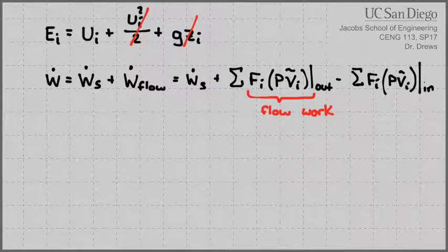That pressure generally is developed in one of two locations. Either you have shaft work, like a pump driving stuff through your reactor, that can be the origin of where that pressure comes from. Or if you're trying to make a Rube Goldberg kind of reactor, you could set everything up really high and let gravity drive it down. That's another way that you could get the pressure that develops in order to force something through a tube. So that flow work in a flow reactor can't go away. It has to be there, otherwise the flow isn't going to happen. In the batch reactor, we didn't care about the flow term because we didn't care how the stuff got into the reactor. We were only worried about what happens once the reactor gets turned on.